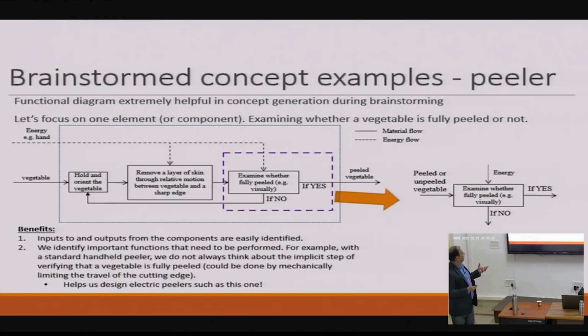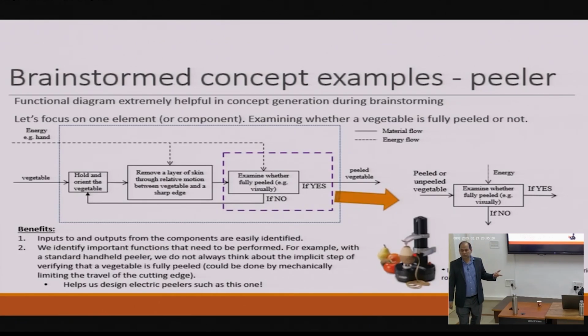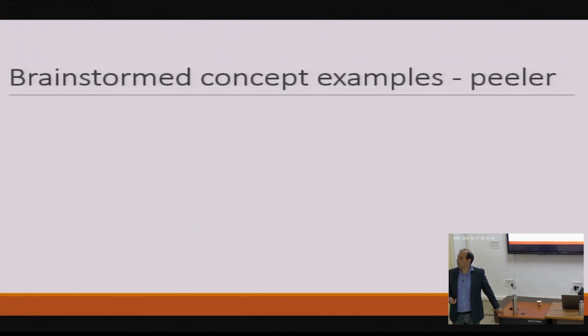We could also just do a mechanical switch, okay? Thing rotates, it hits the switch, turns it off. Okay, so in electromechanical systems, limit switches are all over the place. So that's an indirect way of doing it.